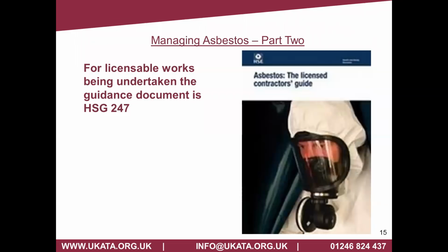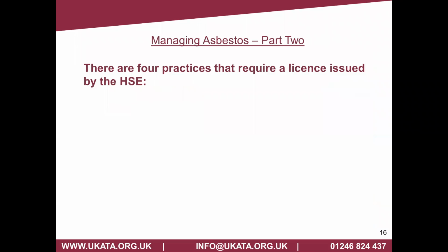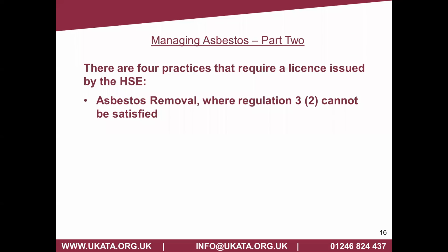Now, so we've mentioned licensed and non-licensed, but we need to break the license side down a little bit further. It's not as simple as that there is only one license issued by the Health and Safety Executive. There are actually 4 practices that require a license issued by the HSE. So of course the common one that we tend to refer to is the removal, where obviously the exemptions under Reg 3.2 cannot be satisfied, i.e. short duration works, sporadic and low intensity exposure, and of course the control limit won't be exceeded.